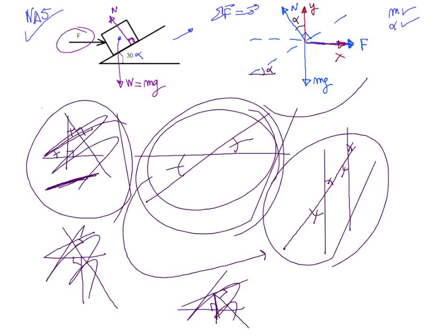Two-step process, two-question process. Identify the two lines that create the limit of the angle that you know is associated with your force. In this case, we know it because we're dealing with the normal force and the angle that defines the inclined plane, and we know that the normal force is perpendicular to the inclined plane. So guaranteed alpha has something to do with n. Identify those two lines and ask yourself, is the force that I'm interested in perpendicular to this line or the other line? It's always one of the two. Once you have identified which one it is, nuke it. Forget about it and focus on the other one.